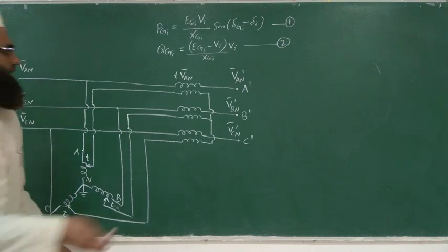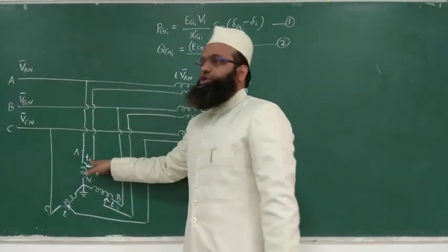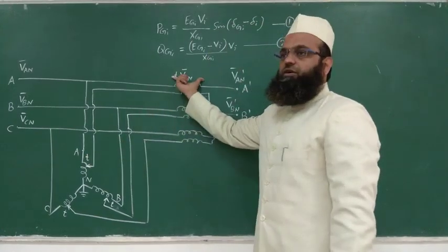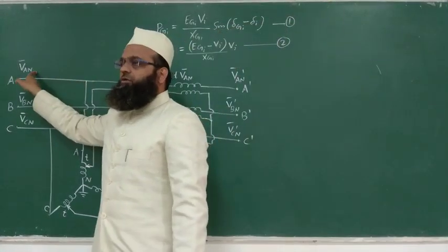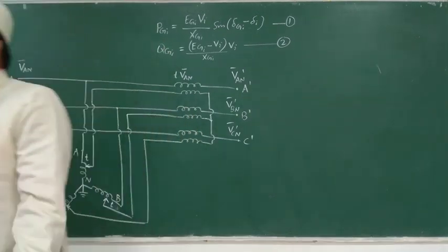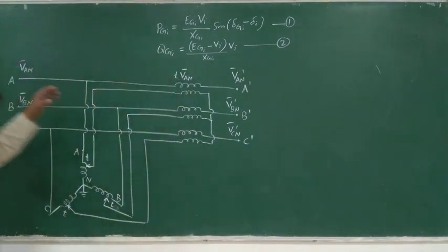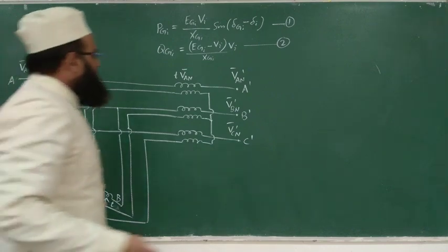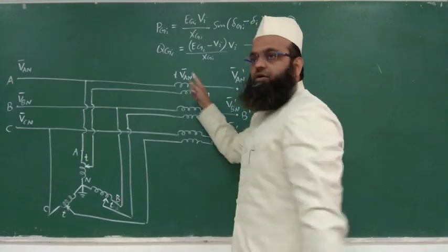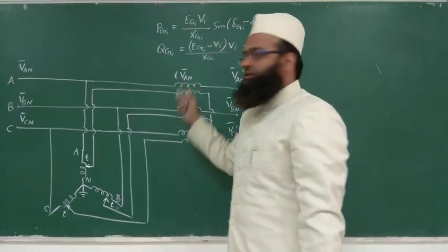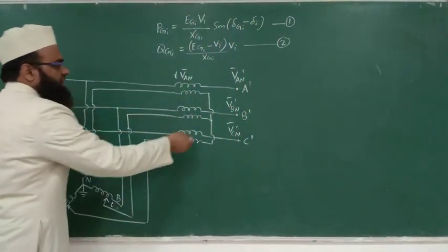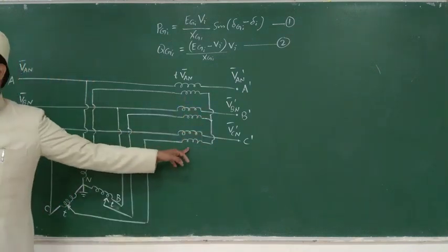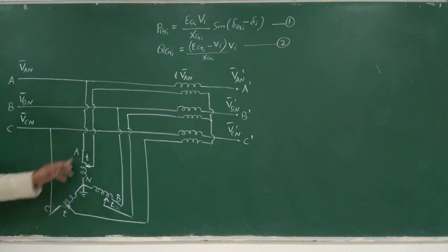So suppose for certain setting T, we are getting corresponding of the same phase voltage T times VAN of the same phase. Suppose tapping is 10%, so we'll get 10% of whatever phase voltage we are getting. Is not it? So basically we are boosting this level by 10% or T% we can say. Similarly for B phase we will have T times VBN. For C phase we will have, because everywhere we have same setting in the three phases.